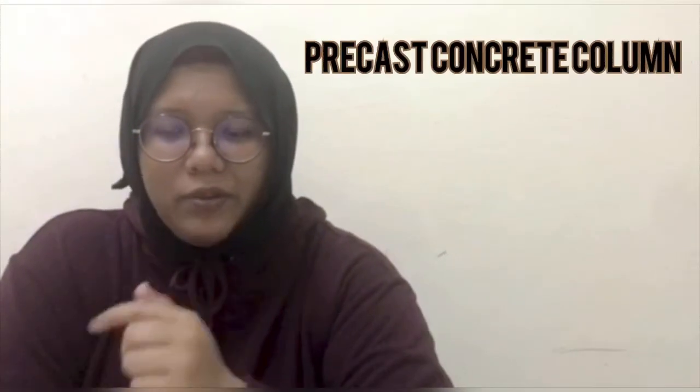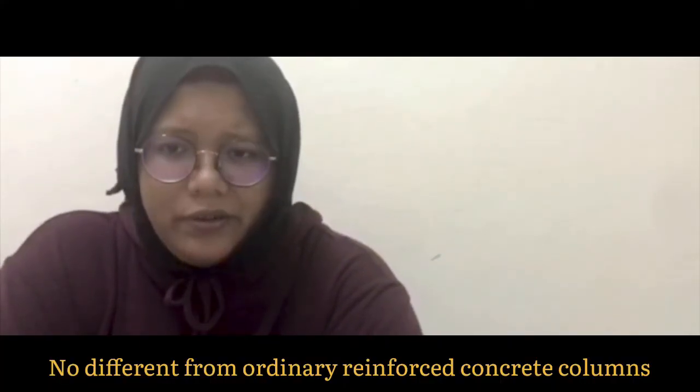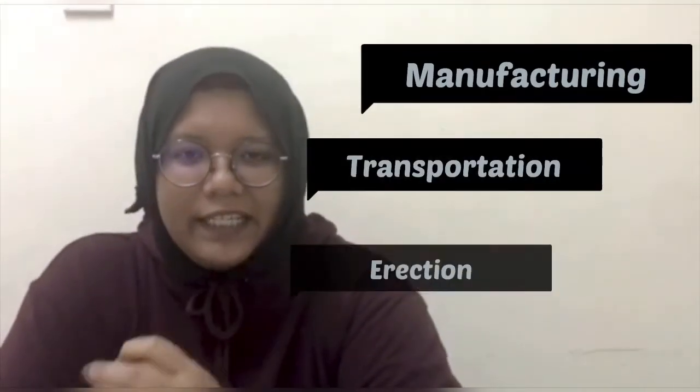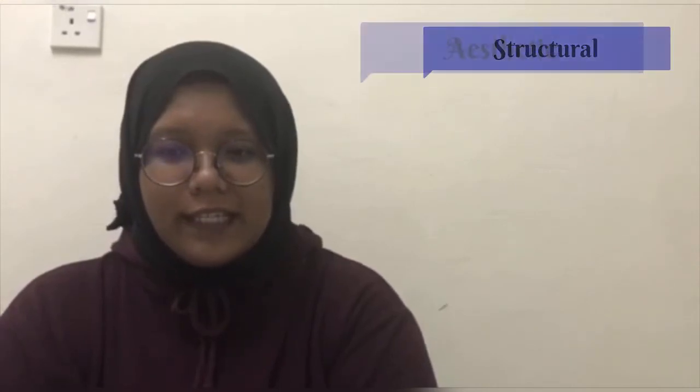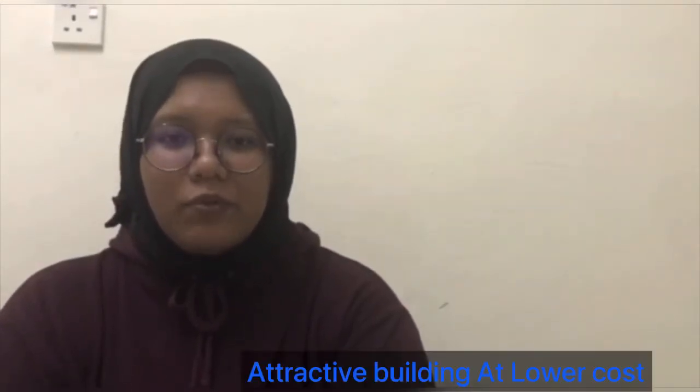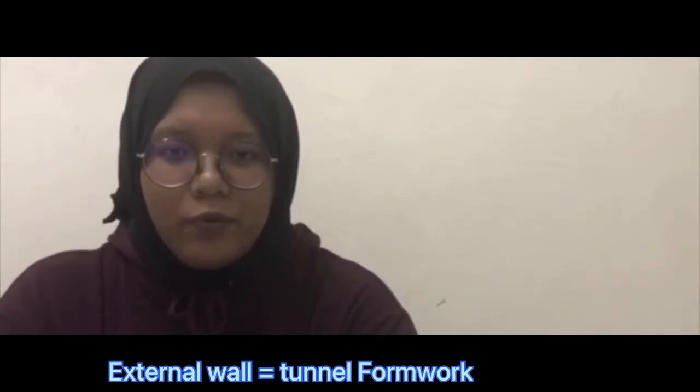Second is the column. The component used is precast concrete column, which is the main vertical load-carrying member in precast structure. The structural design for precast concrete column is not different from ordinary concrete column, but it differs during manufacturing, transportation and erection. For the wall, the type used is precast concrete load-bearing wall panel. It has structural, aesthetic and functional features which make the building more attractive and lower in cost. For internal walls, precast concrete panel is used, while for external walls it is tunnel formwork.